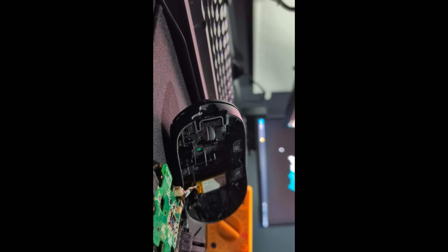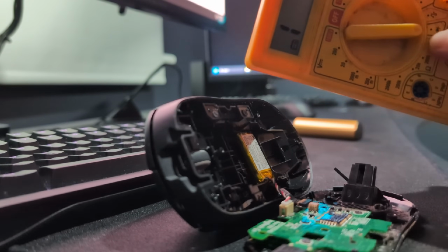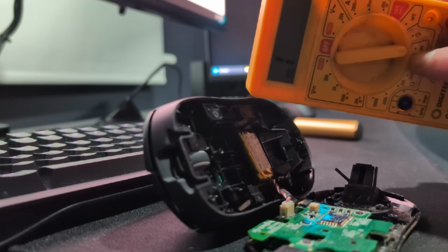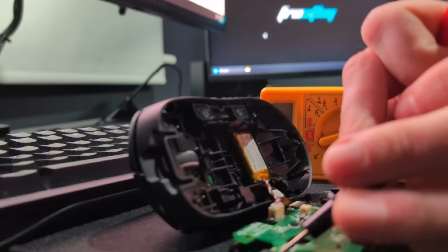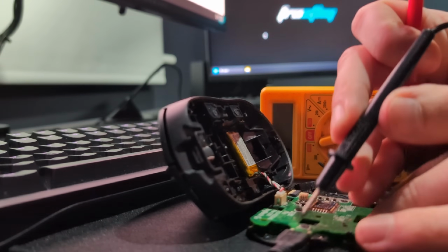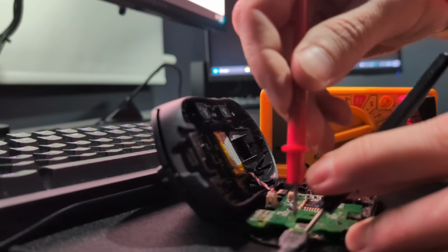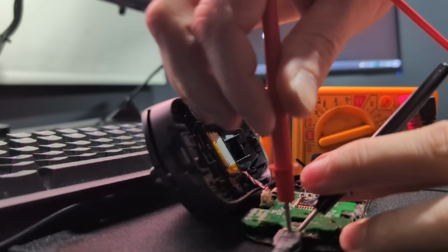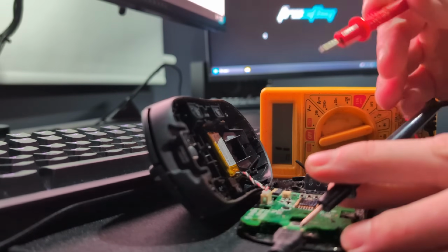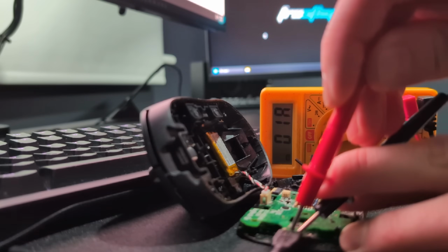The grey one. Once again, using my multimeter, we've got it on the resistance setting. I can't remember what that one's called, but it's like check resistance for earth or something like that. Once again, I'm going to put the black one on the USB housing for an earth. And then if I put the red on the other housing of the earth, we should get a little bit of resistance, that's normal. So we're getting, very hard for me to do, very, very minimal resistance there. So that's earth, right?